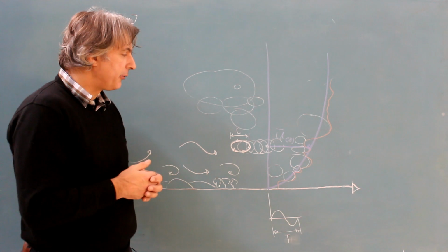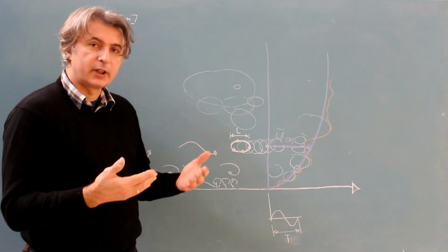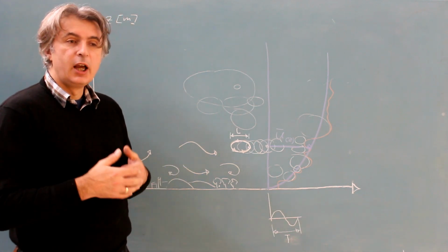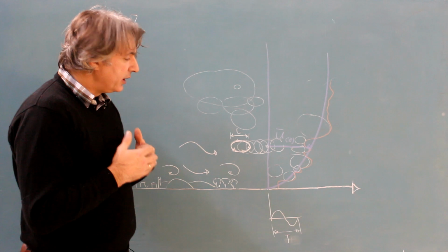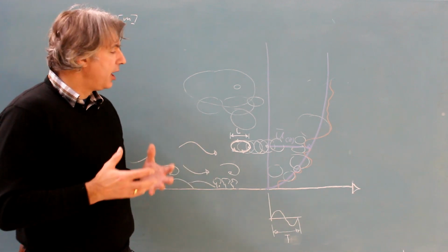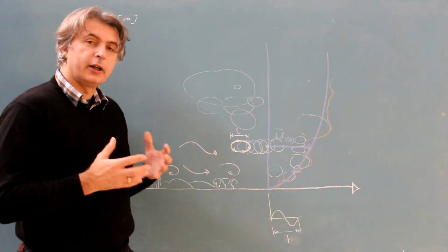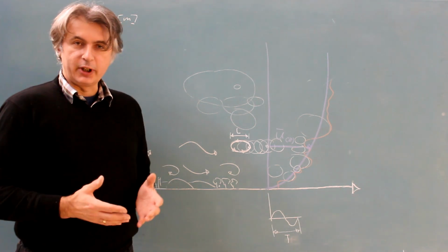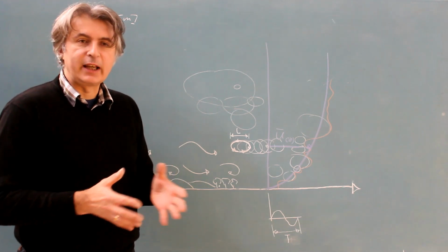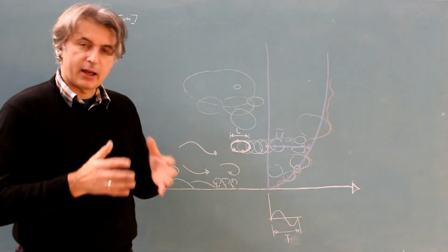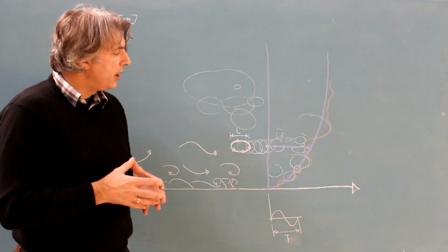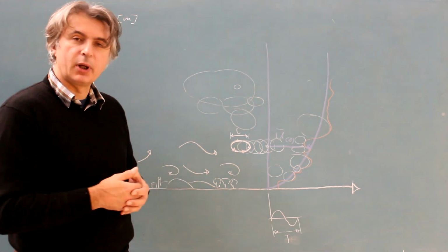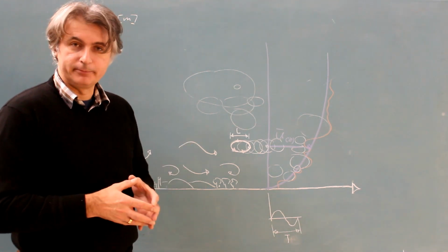From there on, we have to think about how we cope with this resonant effect in dynamic responses, and how much damping we need to dissipate the energy so that we do not have motions in our structure larger than we would like. So this is an alternative to the interpretation of just decomposing a stochastic process, completely abstract, into basic waves. This is the physical interpretation of the wind and how we apply the energy spectrum in this way.